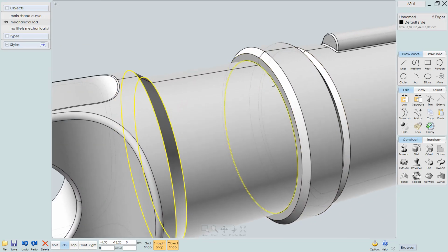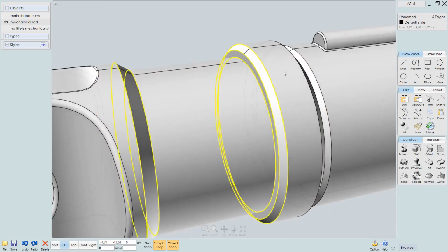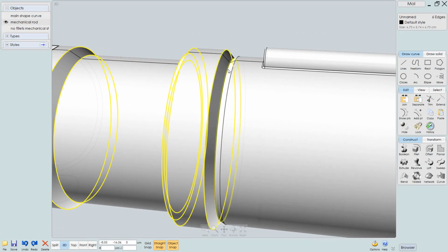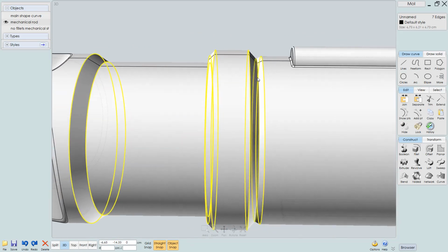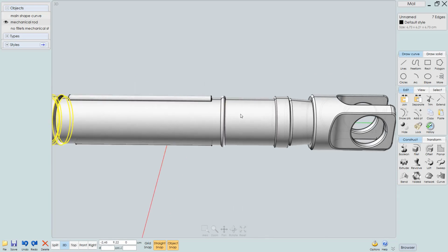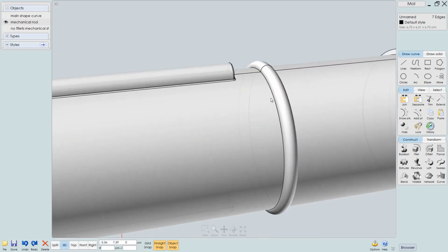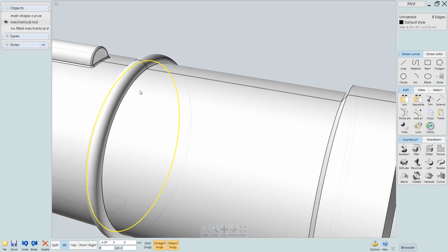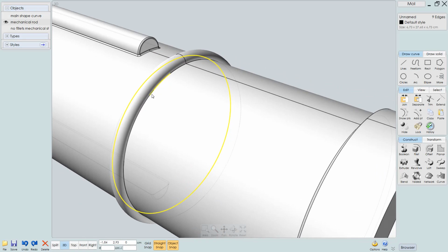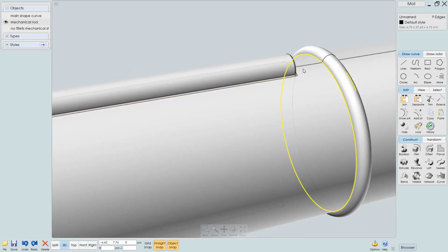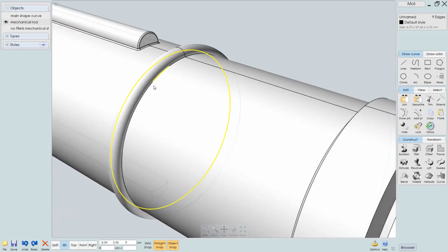And I think I'll just apply the same fillet to all of these, except maybe this one down here. Now over here you can see we have a single edge here, but apparently multiple edges over here. I'll just select all of these, and I'll try to merge everything.